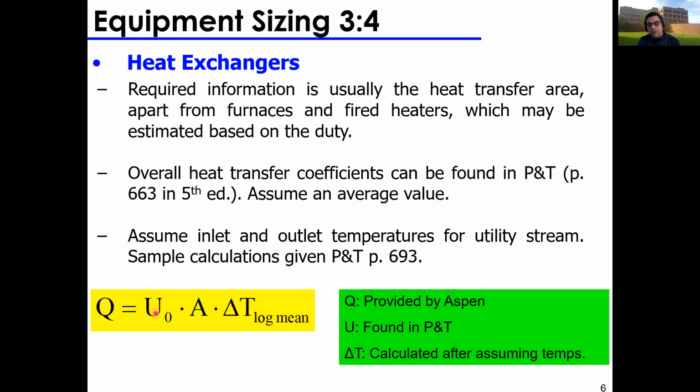You need a special type of material to build this heat exchanger. Are you operating at a very high temperature, at a very low temperature? These will all affect the design of the material, and this will affect your heat transfer coefficient, right? As well as the type of material flowing in your heat exchanger. If you have gases, it's very different than when you have liquids. If you have heavy liquids, it's different than water, all of this stuff.